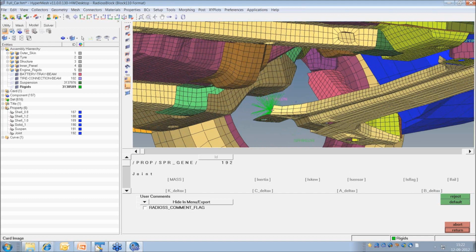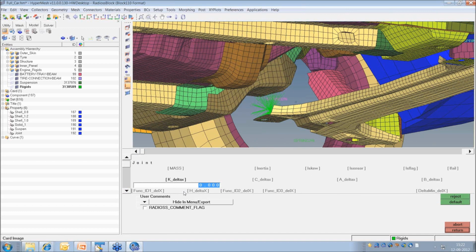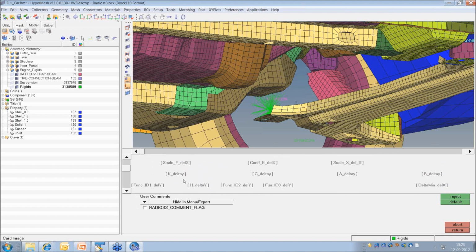in Z rotation. So for that what I am doing is, in all other directions I am giving high stiffness, maybe say 1e5. So this is in the x direction, and this is in the y, again high stiffness.